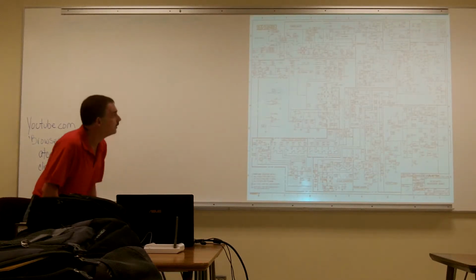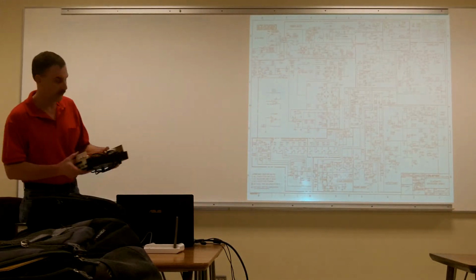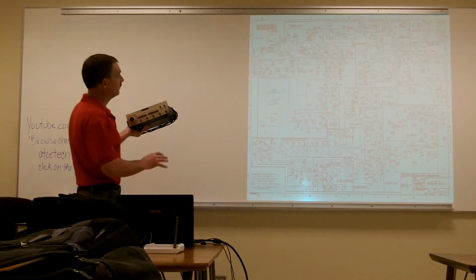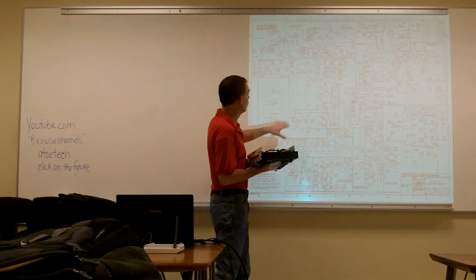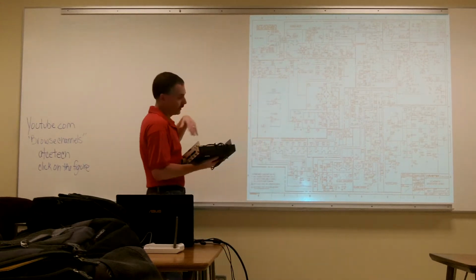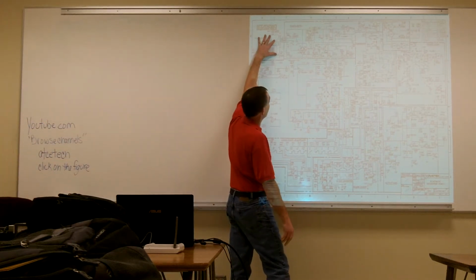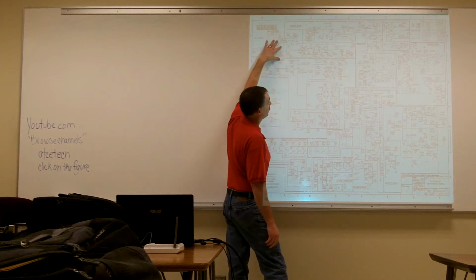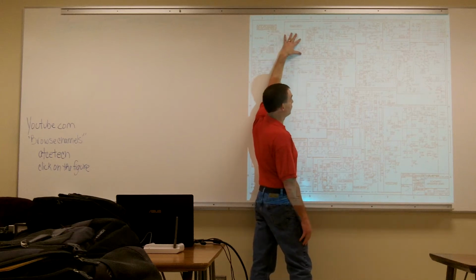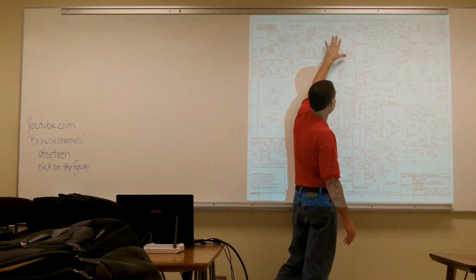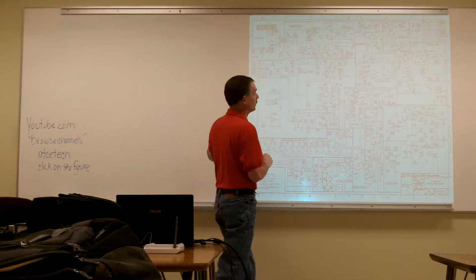So basically, this is the schematic of this wave deck, of this function generator. Right now it looks very complex, but next week we're going to take a little bit closer look at it. It's really actually broken down into several components. We have our 120 volts coming into it. It's going through a step-down transformer. It's taking the AC voltage and bringing it down into our DC power supply. So these first two blocks here are just our power supply.